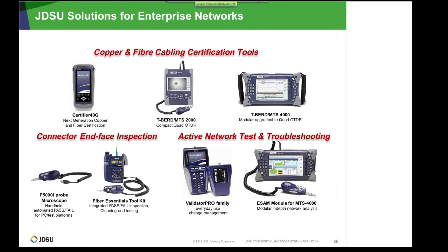This 40G certifier can be used also for fiber certification. But once again, here we are speaking about insertion loss measurement. To detect wrong connectors or to detect breaks or other things, you should perform a standard OTDR. We have such a compact one, even with a quad OTDR. Quad means for multi-mode as well as single mode. The same applies to platform 2000 as well as platform 4000. The difference is just that the larger platform is able to carry 2 modules, the 2000 only 1 module.